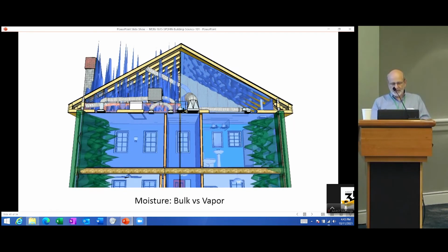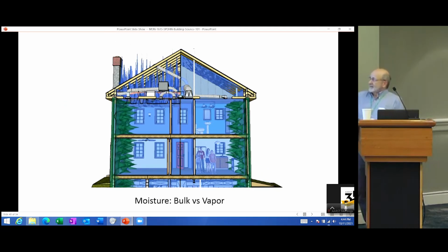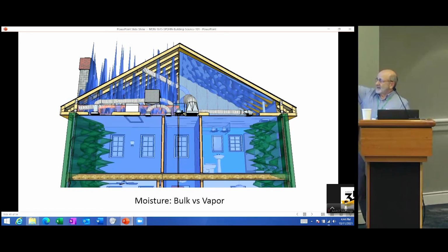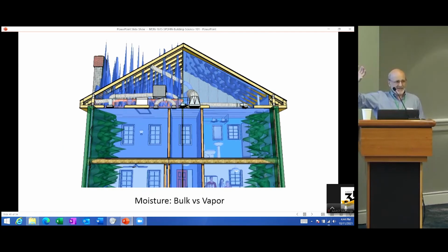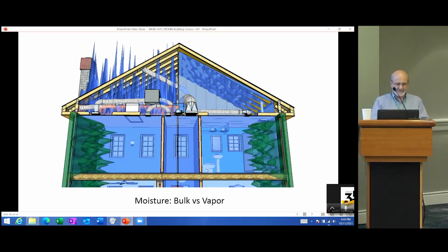So this is zooming in to show how, in this case, a leaky top plate in the attic is actually working for you by exhaling that moisture versus trapping it in. Another thing to realize is if you look at the ceiling joists, the beams there, the ones that are exposed, you really do need to encapsulate fully around the beam, because the temperature difference of that material, if it's not insulated, is going to cause a point of condensation for any kind of moisture that gets in there during the heating season.